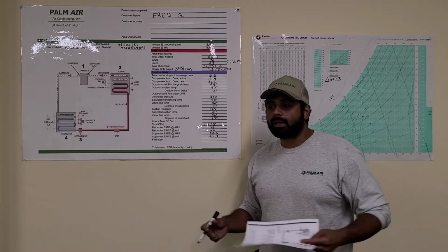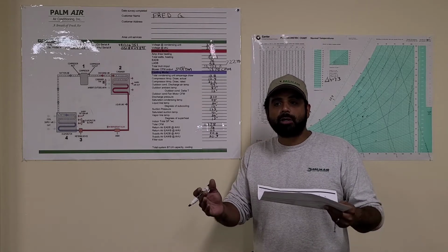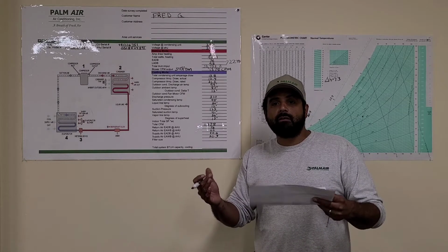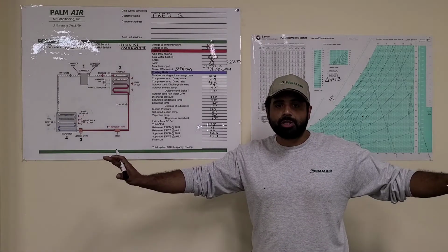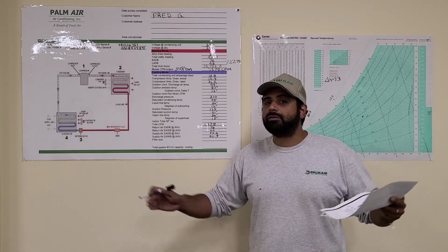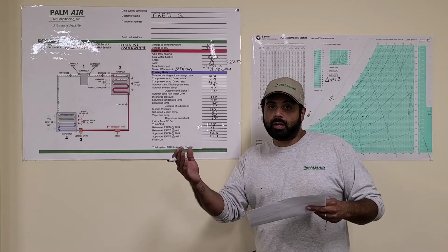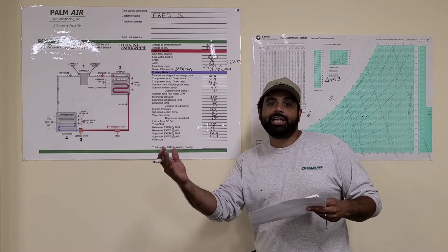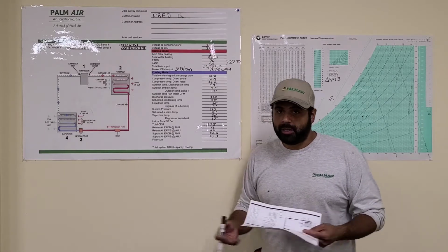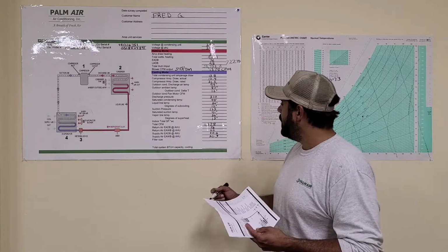As we send warm, moist air across a nice cold evaporator coil, it lowers the temperature of the air. Lowering the temperature of the air forces the air to get rid of some of its moisture. That moisture is then collected onto the coil, goes into the drain pan, and drips out of your condensate drain line outside. That number of latent heat, or hidden heat, and the number of sensible heat combined is total heat, or enthalpy. That's the total amount of heat removed in the air conditioning process.